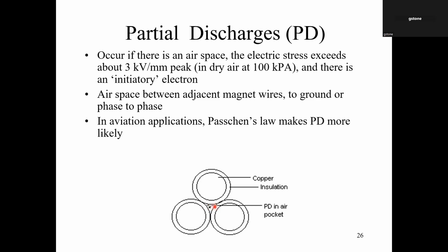And that partial discharge will, because this is purely organic material, it just turns out organic materials are very, very susceptible to aging or destruction, molecular bond scissions in the presence of these repeated partial discharges, the electrons that are going to be hitting that material from the partial discharge. Okay.